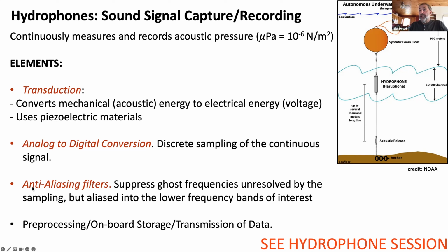There's another more subtle thing I won't really talk about, but once you sample a continuous signal, all of the frequencies that are much higher than your sampling rate can bleed into your signal. So they also have to use anti-aliasing filters. If you don't know what that is, it's kind of an interesting thing to find out about.